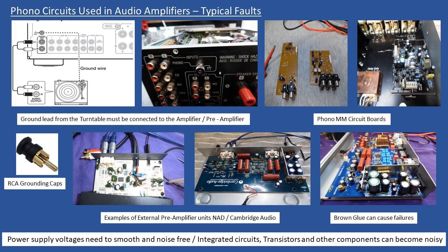So it really comes down to making sure that the power supply design is good, and also ensuring that you have both the correct low frequency and higher frequency filter capacitors in there, and it's not uncommon to have multiples of these. So when the supply voltage comes in, and remember you've got this plus or minus 15 volts to power these circuits, you'll do the high and low frequency filtering, and then it goes into some form of voltage regulation because you need to keep the voltage constant.